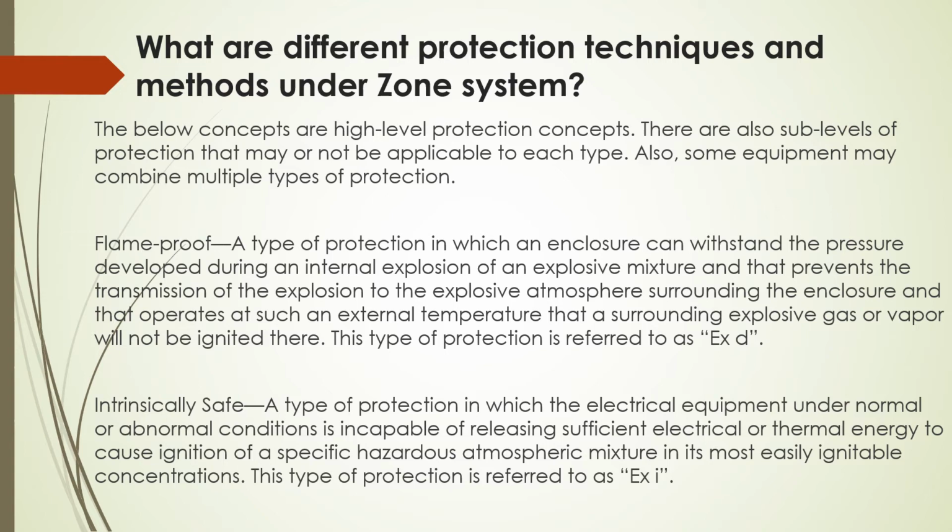Intrinsically safe, a type of protection in which the electrical equipment under normal or abnormal condition is incapable of releasing sufficient electrical or thermal energy to cause ignition of a specific hazardous atmospheric mixture in its most easily ignitable concentration. This type of protection is referred as EXI.